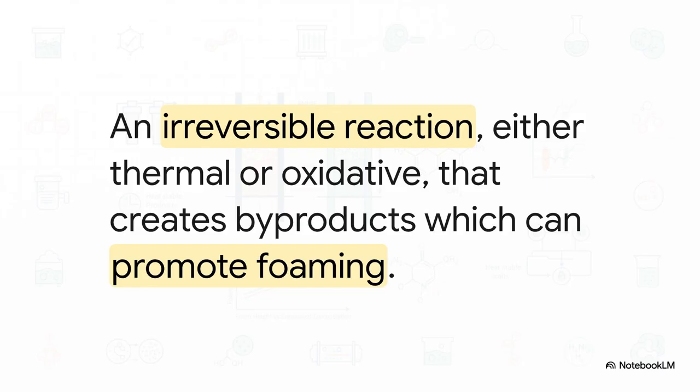In the high temperatures of the regenerator, it undergoes thermal degradation. And if any oxygen sneaks into the system, you get oxidative degradation. Both of these pathways are irreversible, and they create this whole cocktail of chemical byproducts that can completely change the physical properties of your solution.